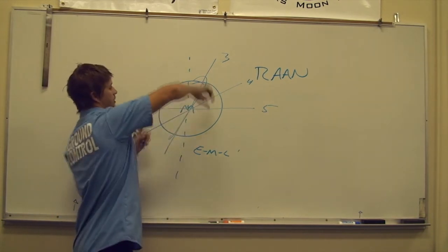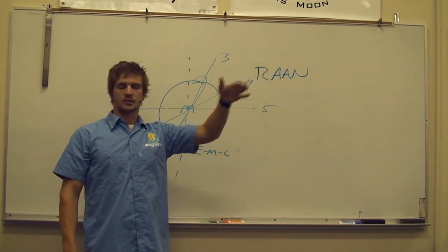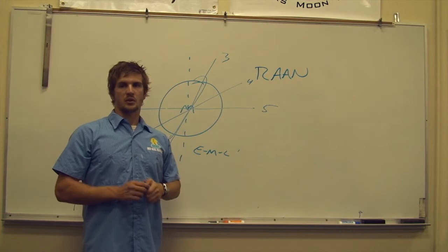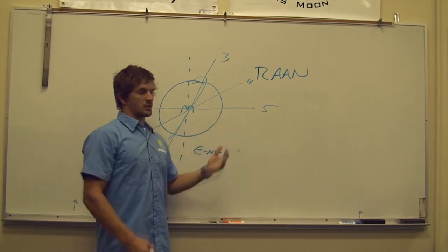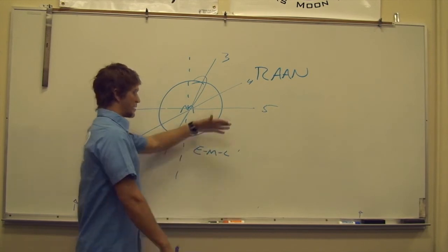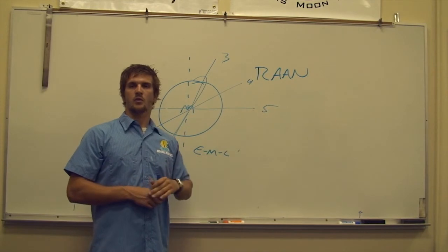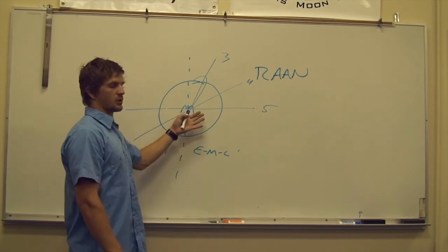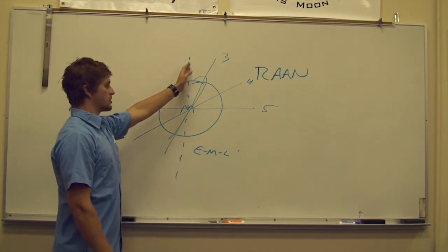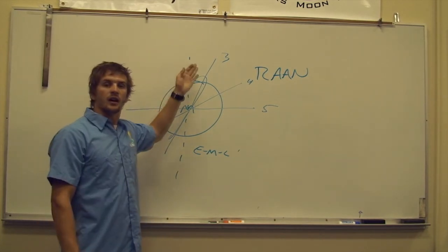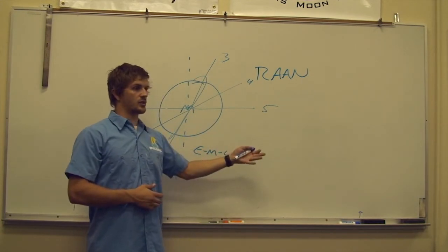So if we're orbiting out here, we can just let the moon rotate underneath us until we line up with our landing site, and we can go ahead and retrograde burn down to the surface from there. And the last method is, like we talked about earlier, phasing orbits. So instead of coming out to the moon, where the risk is a little bit higher and you're further away from home, you can go ahead and do phasing orbits around the Earth and buy yourself some time, and maybe you can essentially plot your trajectory straight on this Earth-Moon line. The final thing we're going to talk about here is the descent down to the moon's surface.